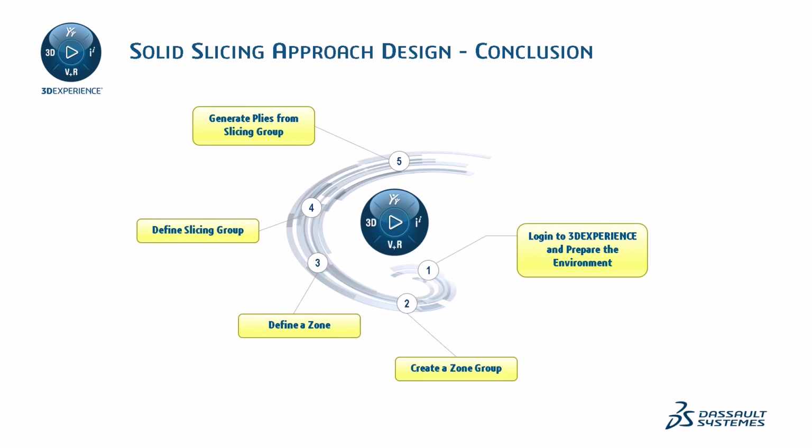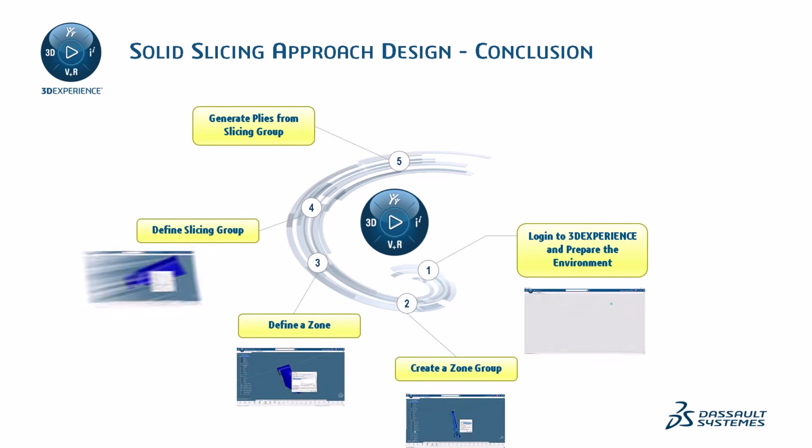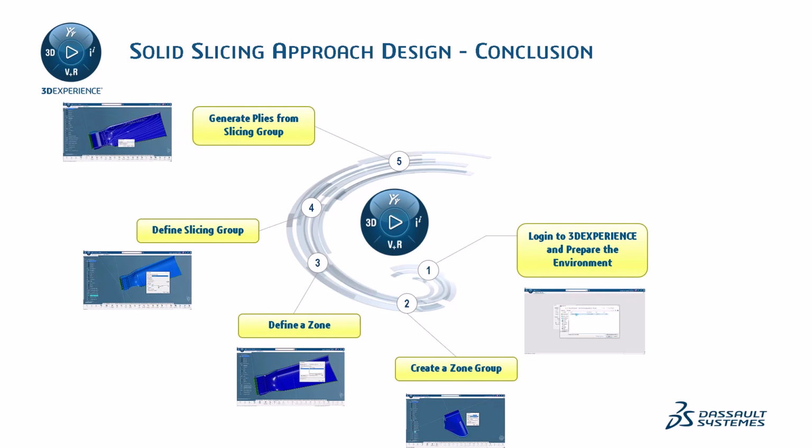This is the end of the tutorial. In this video, you learned how to log into 3D Experience and prepare the environment, create a zone group, define a zone, define a slicing group, and finally, generate plies from the slicing group.